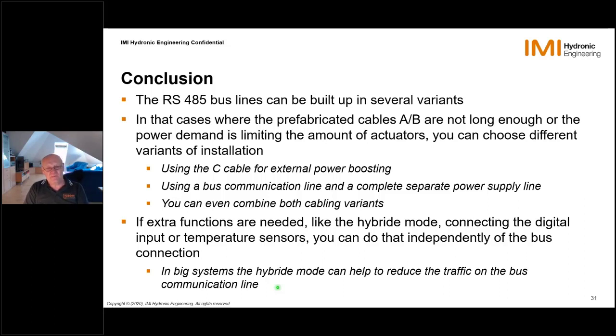And especially when you have quick reacting systems like air handling units, then you need a quick reaction of the actuators, so that not the cold temperature, for instance, is going out from the air side of the air handling units. So that's important to know, and we have to respect the physics around these things, and therefore we can have long lines, we can choose some things, and it's important that you know that we have different solutions. So in that case,